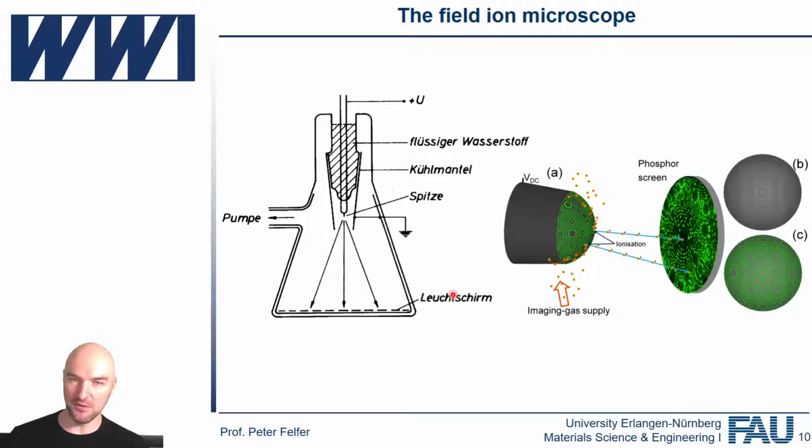And the vacuum you actually need to establish for field ion microscopy isn't actually that brutally high. So you usually get away with 10 to the minus 7, 10 to the minus 8, 10 to the minus 9 definitely. If you have a vacuum system with a turbo pump and some rubber gaskets, that's sort of the level of vacuum you can get to anyway.